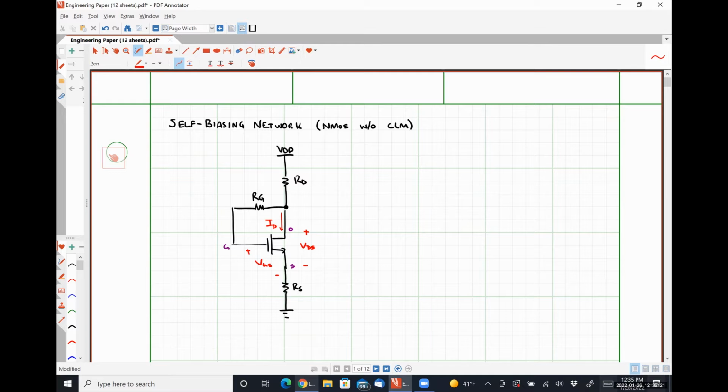So assuming this device is on, what is literally the only operational mode it can have? Saturation, exactly right. Would you care to explain why, Logan? I don't remember, but I know it's because of the feedback between the gate and the drain. Okay, so we have established that no gate current can flow in this device, right?